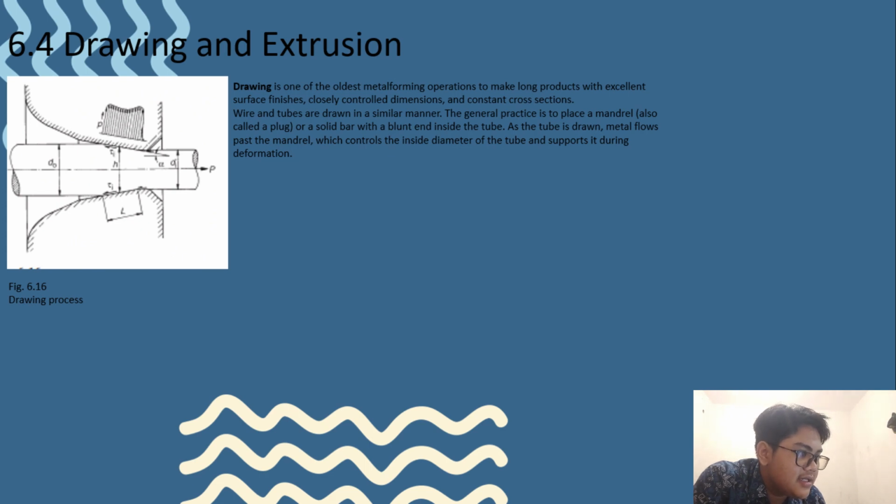This is generally greater than 60% of the absolute melting temperature of the metal. The hot extrusion process is used to produce metal products of constant cross-section, such as bars, solid and hollow sections, tubes, wire and strip, from metals that cannot be formed by cold extrusion.